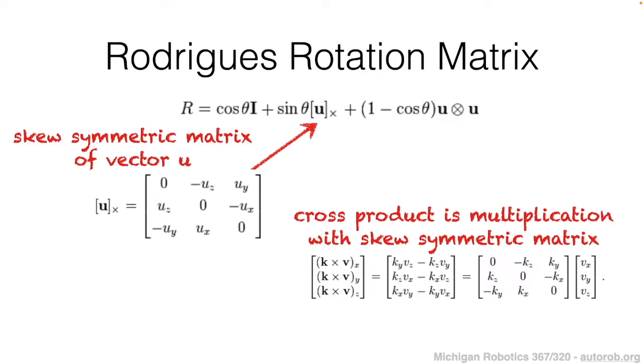The equations shown on this slide, I'm not going to walk through in too much detail, but the key takeaway is that we can implement this Rodrigues axis angle rotation transformation as a series of matrix vector operations. And the benefit once again is that we don't have the issue of Gimbal lock and so forth that we saw with Euler angles.